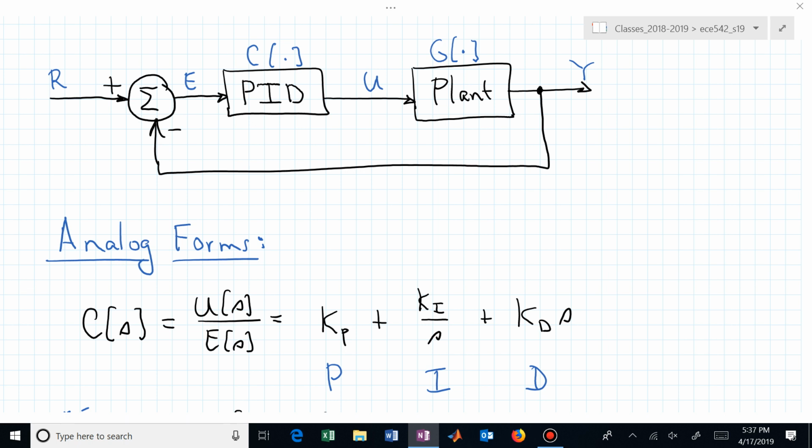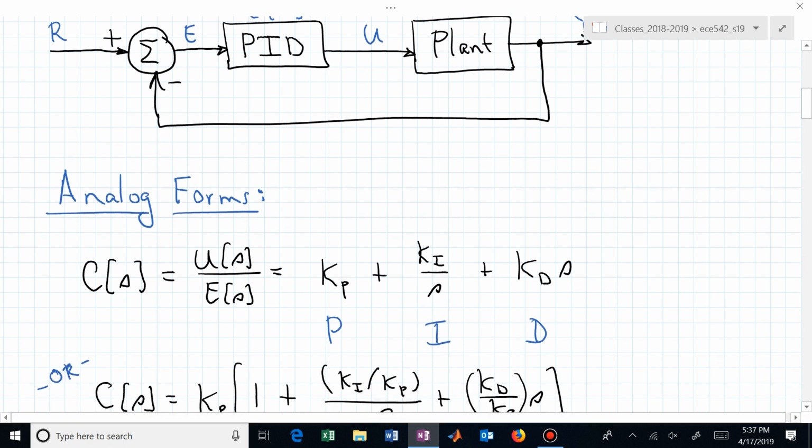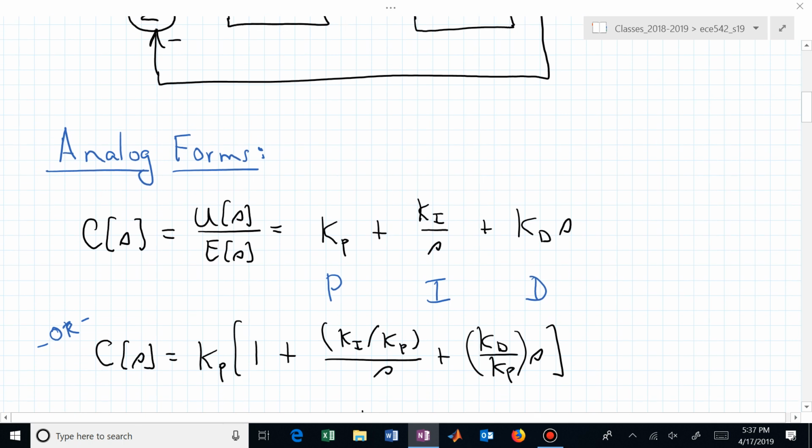And what does the P term influence? The error at the present time. The I term is integrating up the errors from the past up until now, and the D term is sort of the anticipatory term. The I term is good for improving steady state accuracy, removing error in your system. The D term can be used for speeding things up.